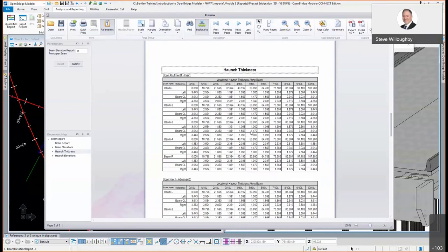At the center line here, since this particular beam rests right under the crown point, or the profile grade line, both flanges are right at that 1-inch haunch value here. And then the right flange happens to come into and be the controlling point, as we would expect at midspan for the two beams on the right side of the deck.